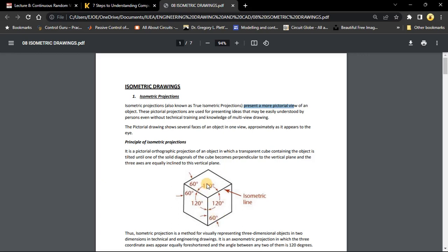And in so doing you are able to see more like three elevations of the said object we looked at in orthographic. So with isometric you are able to see all three at the same time, meaning you can see the plan, the front elevation and an end elevation at the same time. So the key feature here is that one of the axes has to be vertical and the others will be 30 degrees to the imaginary horizontal line. So that is what we keep in mind.